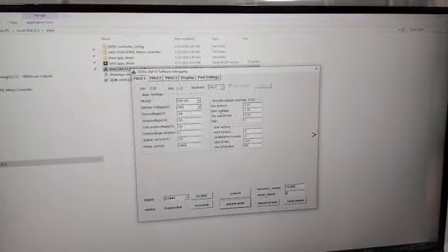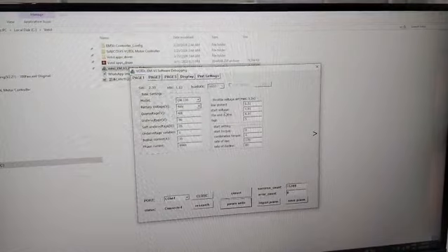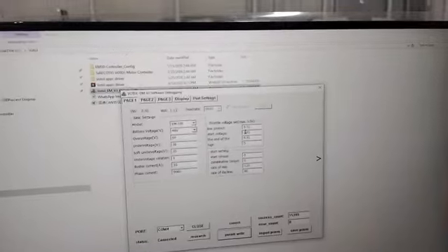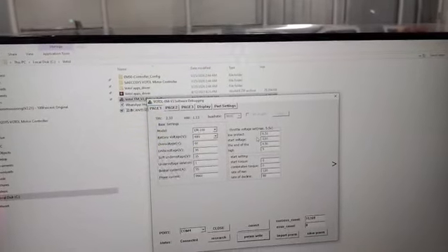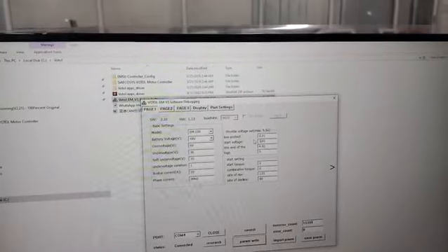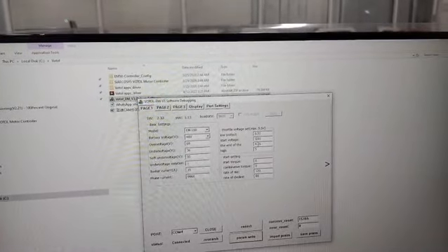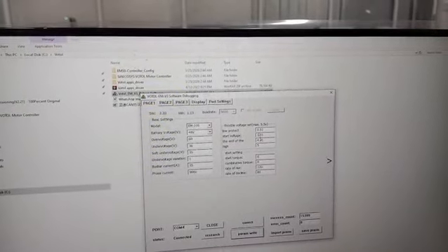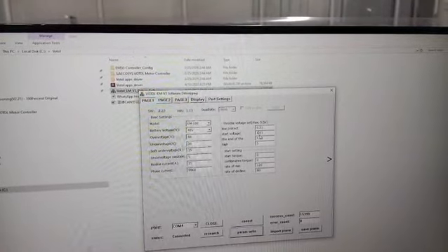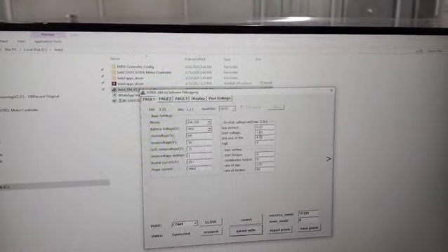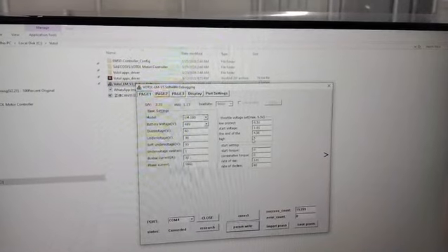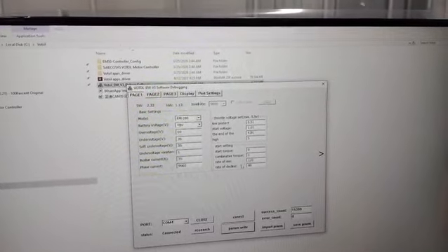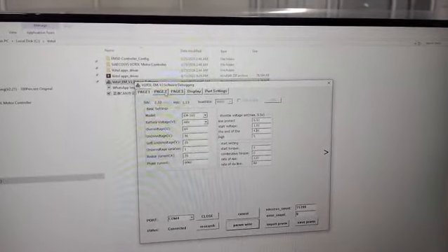So basically for 0 voltage we cannot start the throttle. So basically there is a buffer. So we have start voltage up from 1%. We have to take the throttle from 1 volt to 4 volt. We cannot give an exact voltage, so from 0 to 5 we have to make some buffer. So here is 1 volt for lower voltage, 4 volt for end voltage, or maybe you could say high voltage. So that is the start setting. Here is the throttle setting.